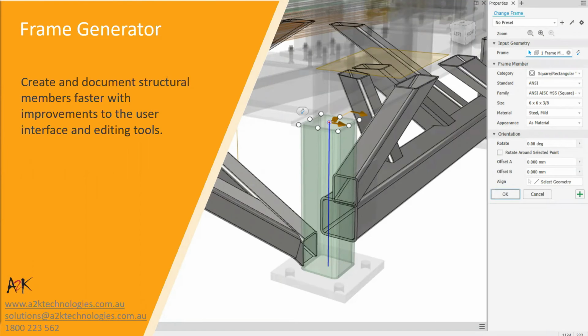The frame member trim tool has been improved, enabling you to trim to a curved frame, and new end treatments have been added. So there have been 2 new profiles added, I, T, and C profiles, as well as circular members. And the frame member reuse command has had a significant overhaul, making it easier to reuse your frame members to populate your skeleton geometry.